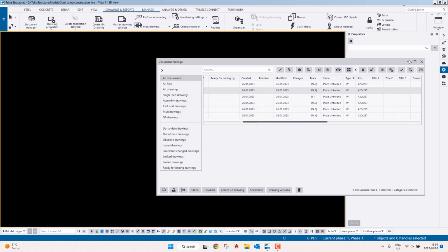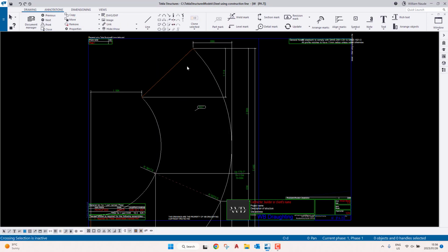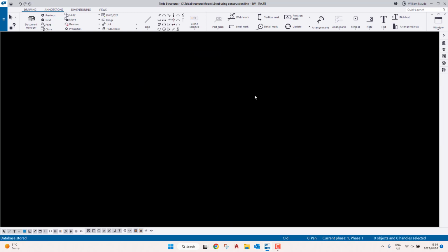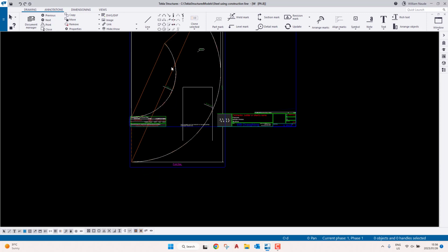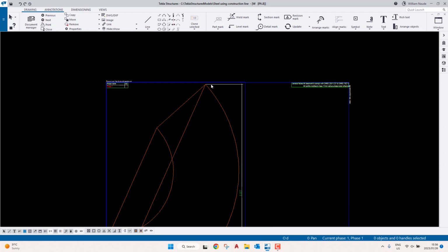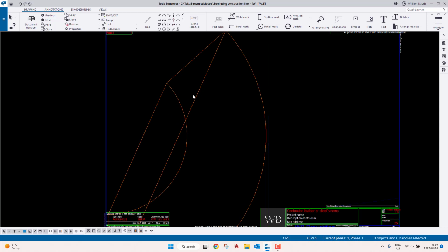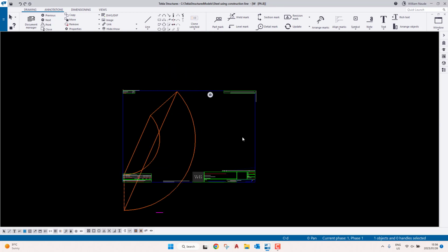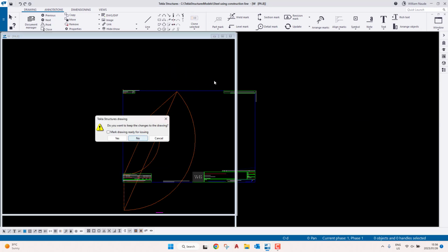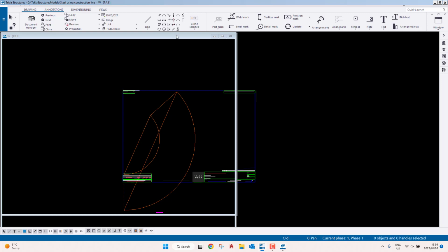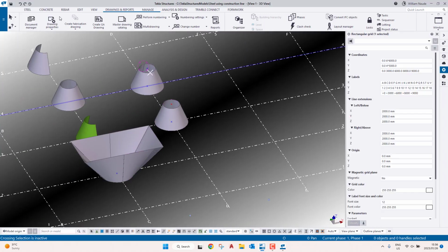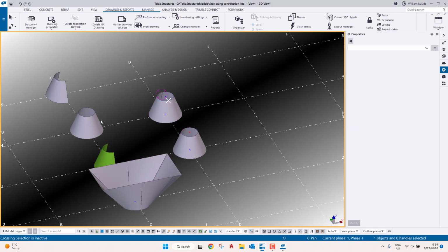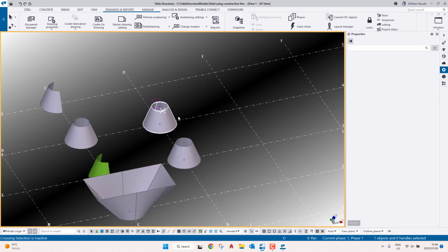Okay, so let's open it up. Right, so as you can see, this is the one, PA7, and we're going to go with previous, and now PA8. As you can see, this is not correctly done. I don't know why it has this line right here, as you can see. So this is not how it should look. And once you create your NC files, this is what you'll get. So I'm going to show you now quickly. As you can see, using the circle function, you can't unfold it. So rather use the standalone function, or even this function.